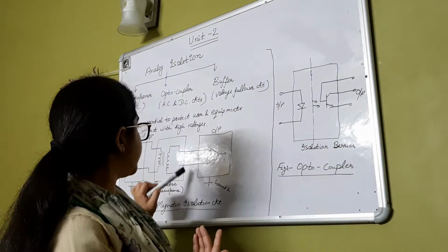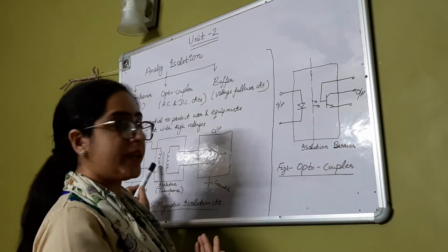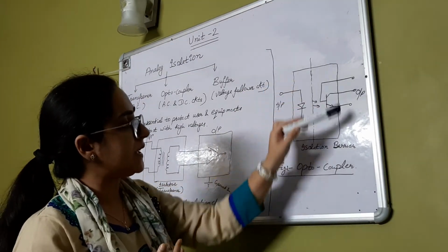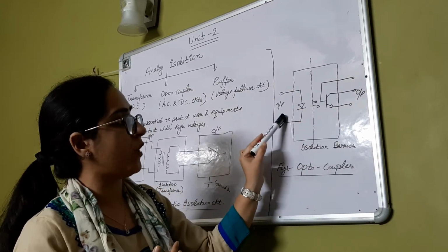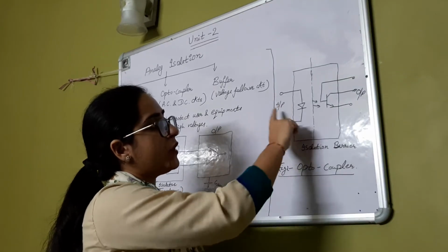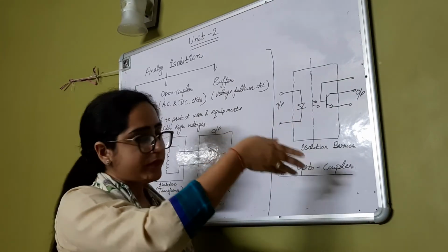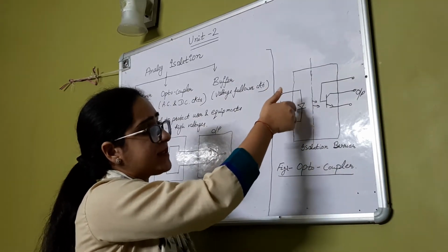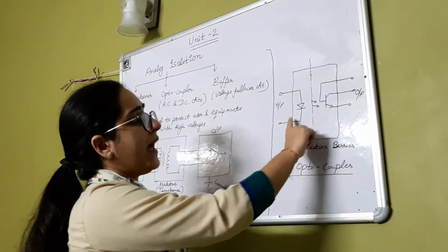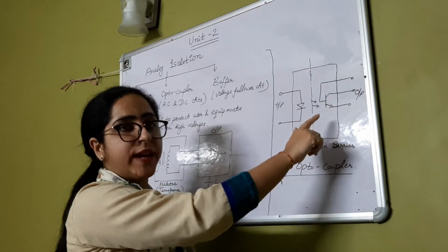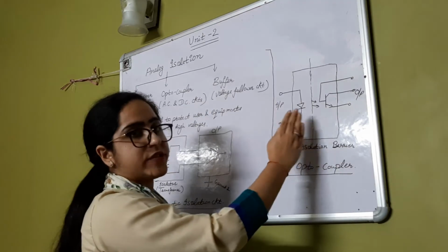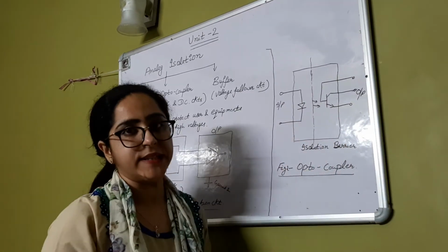The same principle is for the transformer, where through magnetic coupling the output voltage follows the input voltage. And similarly, in the optocoupler case, the output voltage follows the input voltage. If there is any change in the input voltage, the current through the LED will change, and due to the current change, the intensity of the light will change. Accordingly, the light detected by the photodiode or phototransistor changes, and so the output voltage. So the electrical signal is traveling through the medium of light, right?